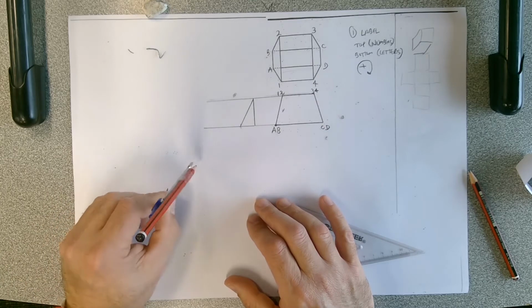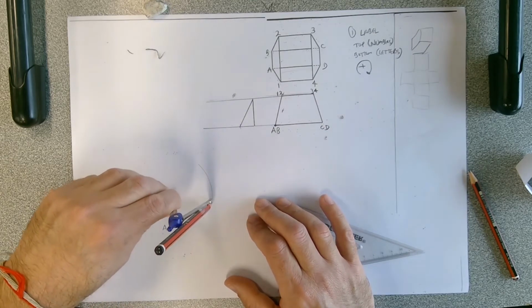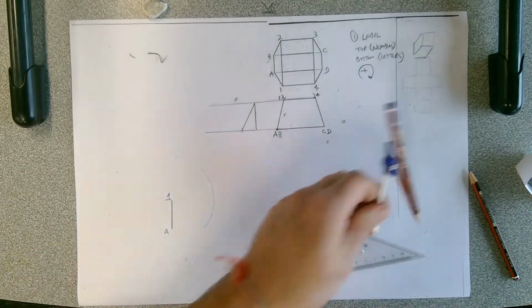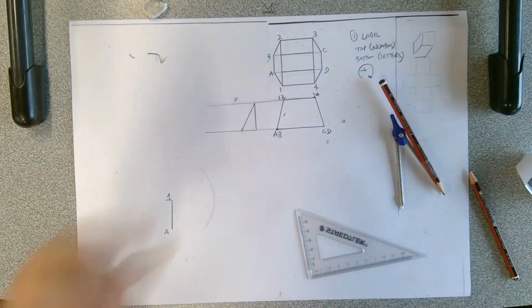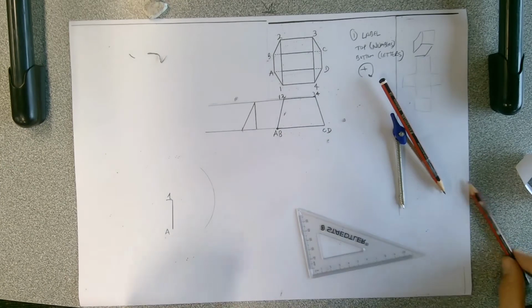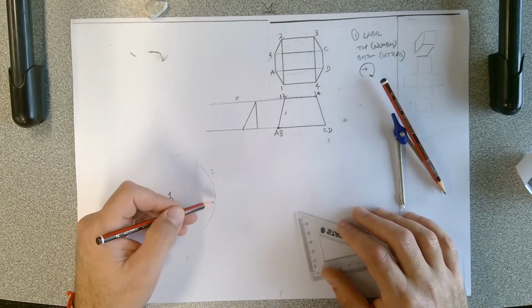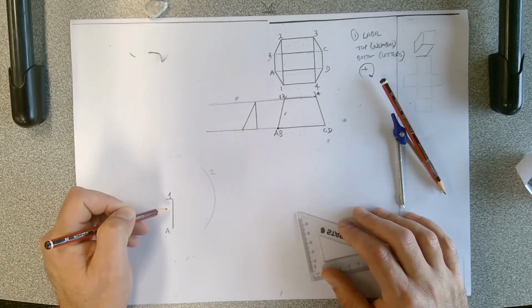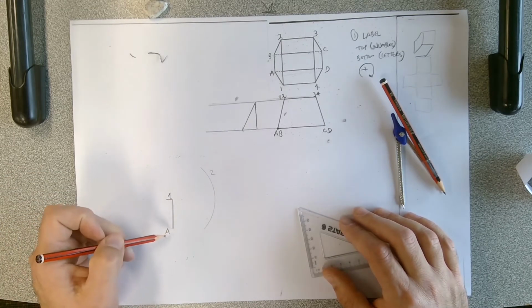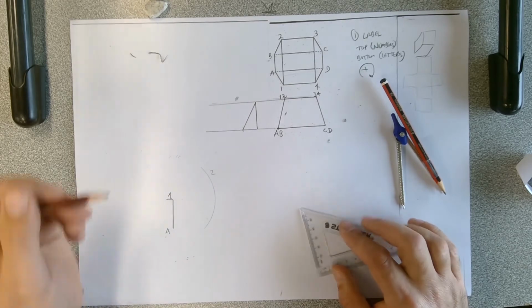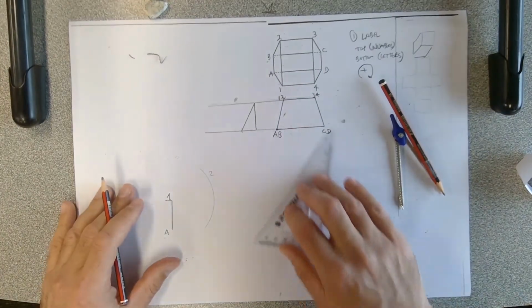Now swing. Whenever you swing an arc, swing it big, because you'll be surprised by where the intersections are going to happen when you actually have to work that out. So swing a big arc. Okay, 1, 2. So this is going to be going from 1 to 2. But where do we know on that arc to draw the line between 1 and 2? We need to find another point that goes to the point 2. And the way to do that is, this is where the triangulation comes in.